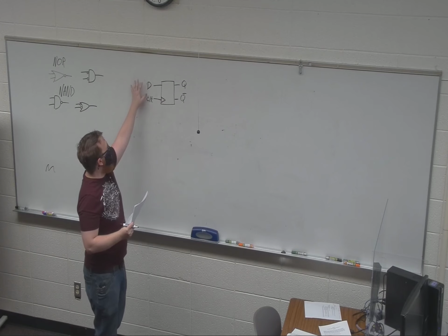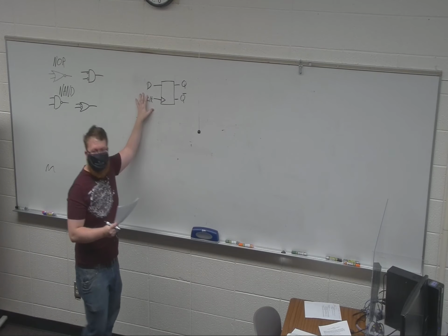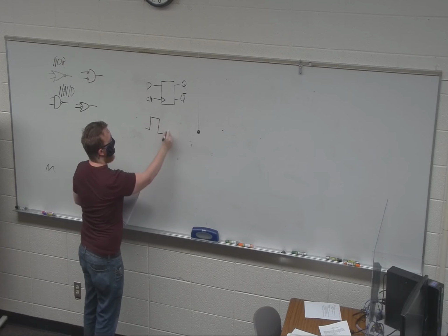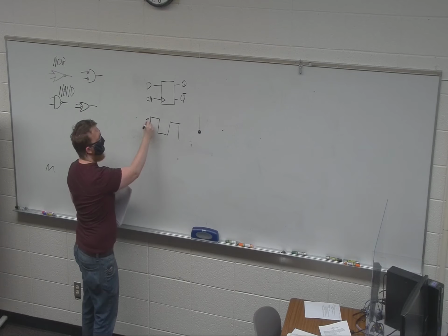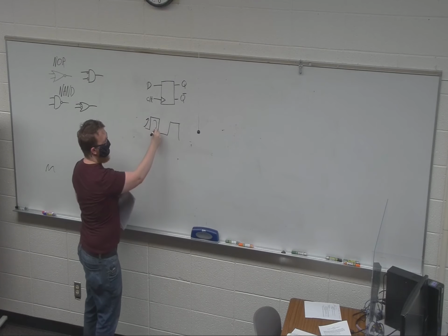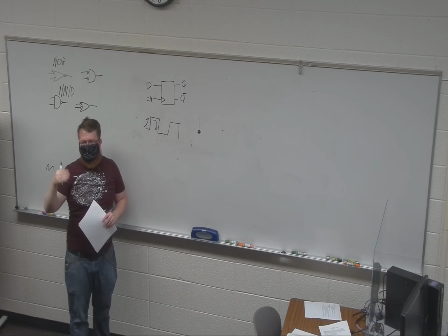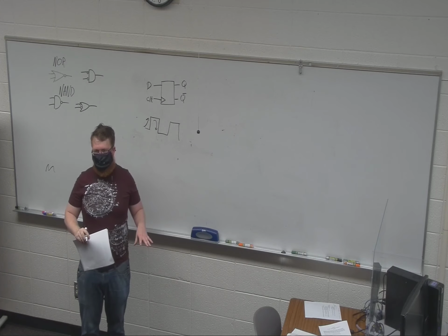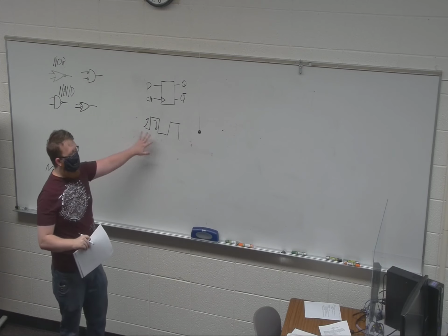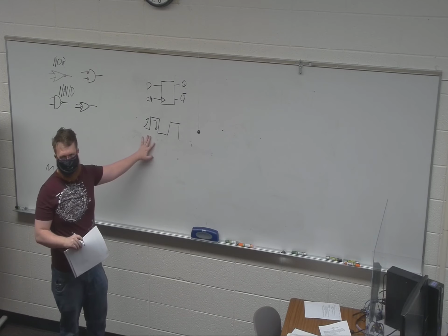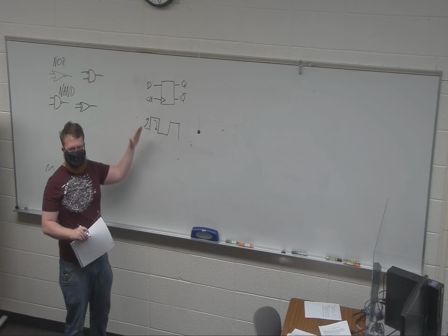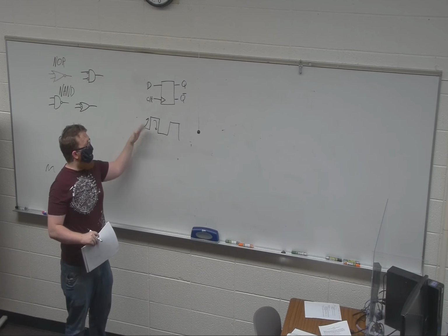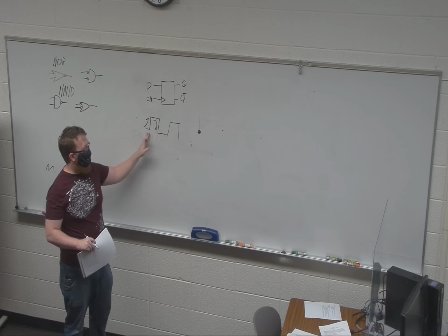It worries about when the clock hits, and the clock can be either positive edge triggered, meaning something happens on the rising edge, or negative edge triggered, meaning it happens on the negative clock. And in systems, which is what we're looking forward to, you are going to have both types of devices. The positive and negative clocking is useful to make two things talk to each other, because you can have one flip-flop load in on the rising edge, and the next flip-flop take the data output on the falling edge, so that it can pass along pretty quickly without having to wait for each clock.